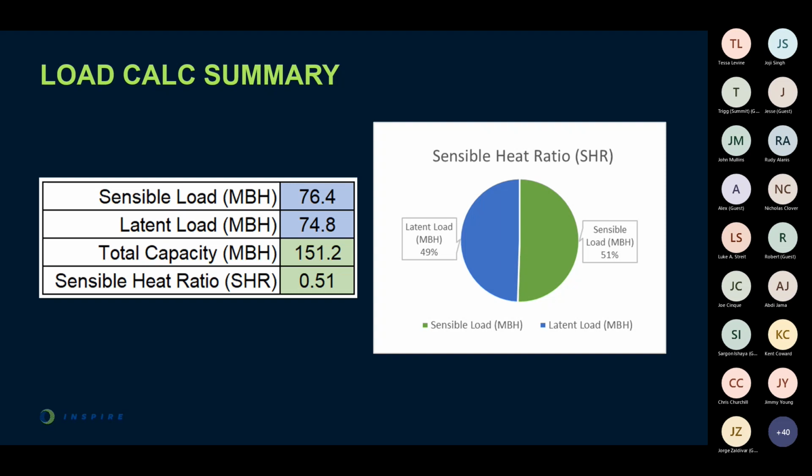And as a result, almost all HVAC units today on the market have an SHR of about 0.85, with 85% of their total capacity going to cooling and only some going to dehumidification as a byproduct of the cooling process. So this SHR here is why we had to design purpose-built integrated units to serve indoor plant environments, because they really have a different need than most other spaces.